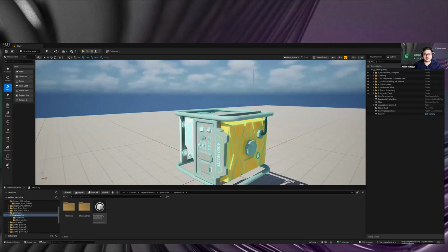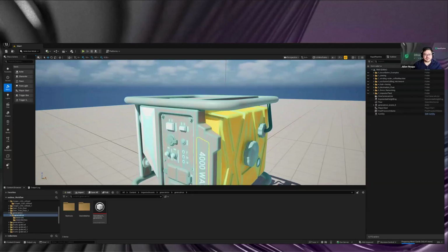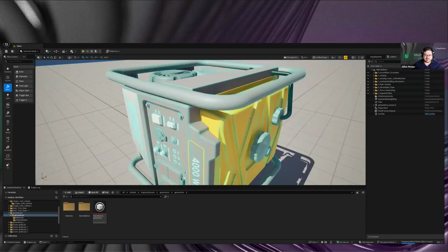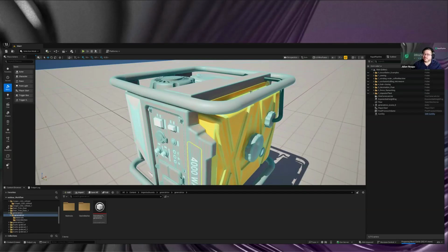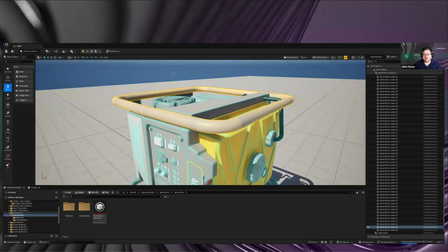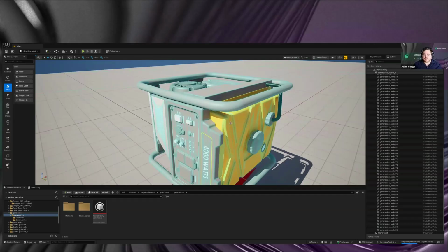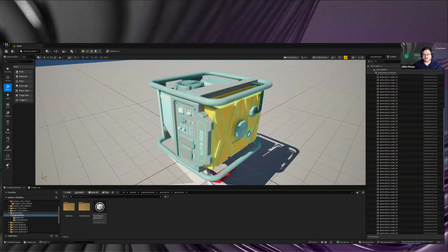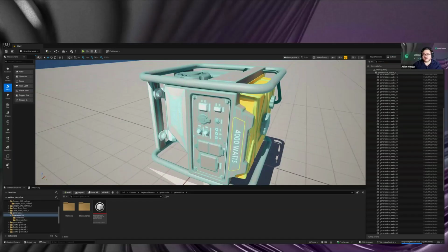Yeah, so in this case, this was the fine tessellation, so we could adjust that as well. One feature we don't have yet, but we're actually working on, is retessellation. So if you have a problem with a certain tessellation result with the parts, you can retessellate it. For now, that's not available, but as I said, we're looking into that at the moment. But our general approach, usually, if you don't go too low with the tessellation resolution, as I mentioned before, then you usually don't have issues with certain parts being under tessellated. It really depends also on what preset you use.